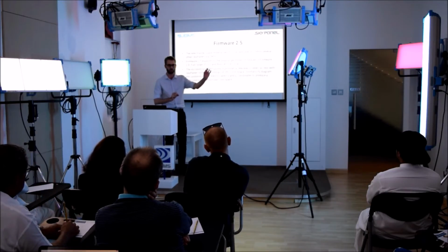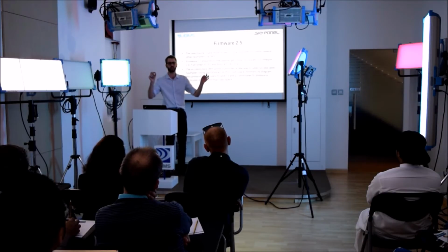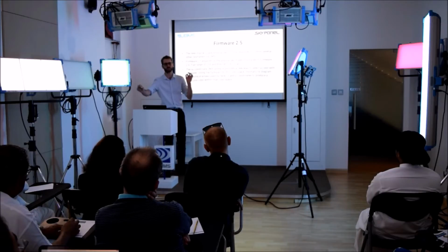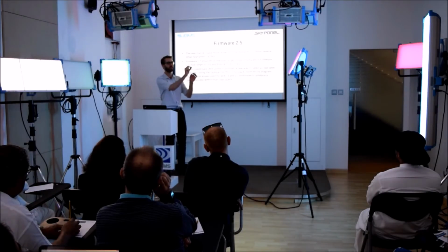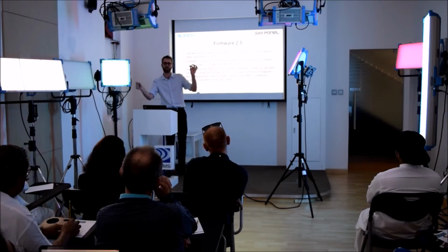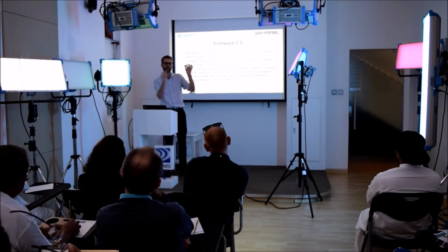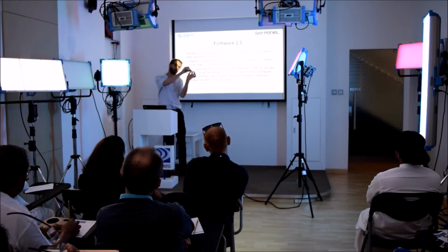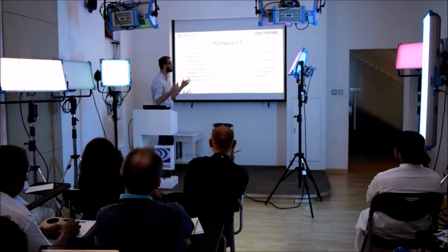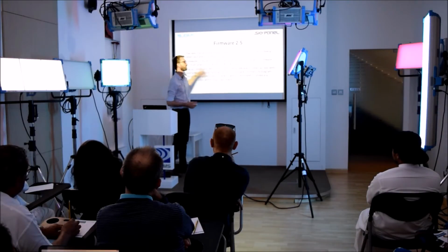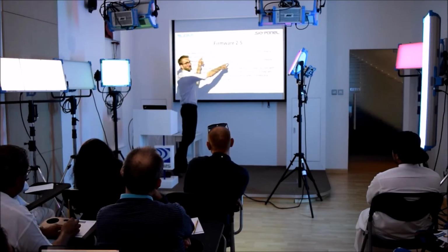You can select one set of XY coordinates, or one color, as color A, and another second set of XY coordinates as color B, and then you can have the light automatically go from color A to color B. And it can do it in different ways. It can go through the white point in the middle, it can go around the white point underneath, or it can go above the white point. Anyway, I'd have to go back to that chart, but if you look at that color chart again, with the white point in the middle, it means you can select color on the chart over here, color on the chart over here, and the light will automatically fade between one or the other.